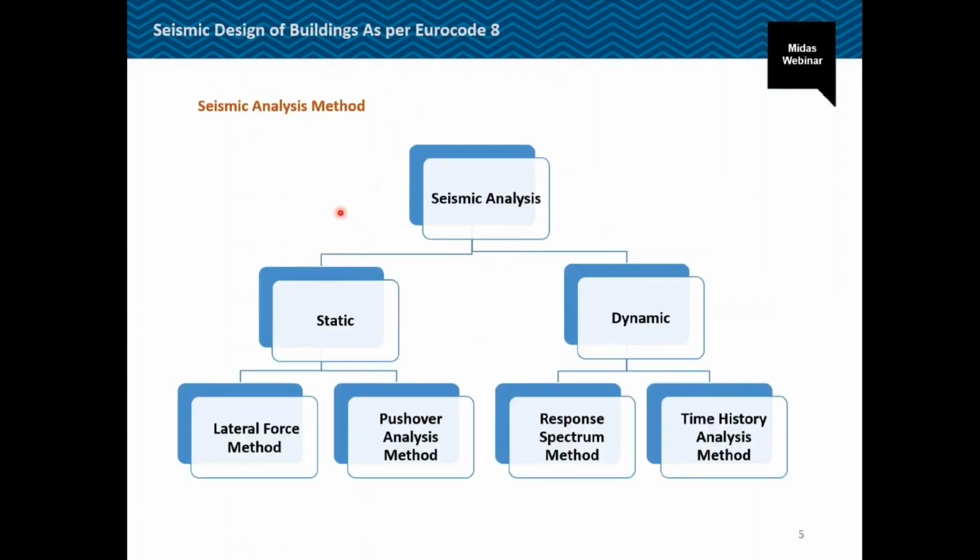So these are some of the methods using which we can perform the seismic analysis. This is the static method and these are the dynamic methods. In the static linear analysis method we have the lateral force method, and in the static non-linear analysis method we have the pushover analysis method. In the dynamic linear analysis method we have the response spectrum analysis method. Then we have the non-linear dynamic analysis method, which is the time history analysis method.